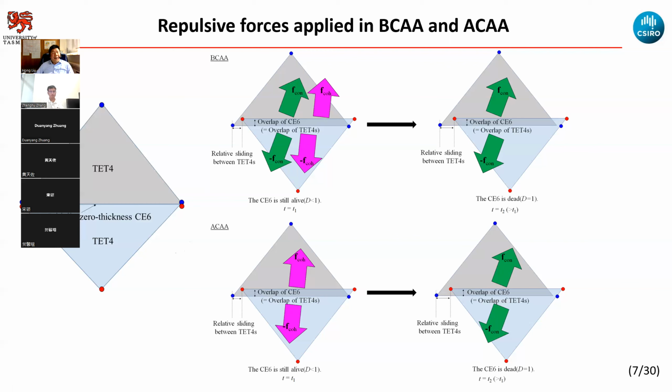So we tried to understand the mechanism. Obviously, it does not happen in the opening, mode one, because when opening, the surfaces completely separate from each other. It happens due to the contact, since the contact force prevents penetration.